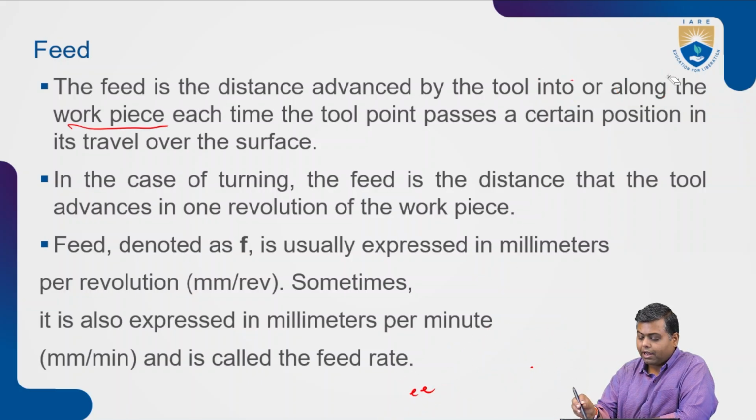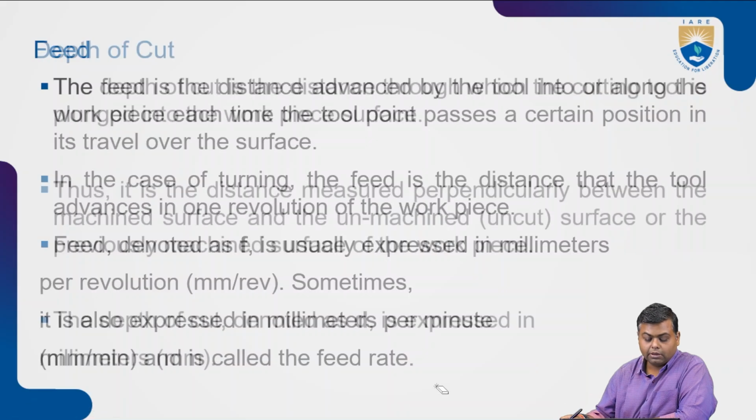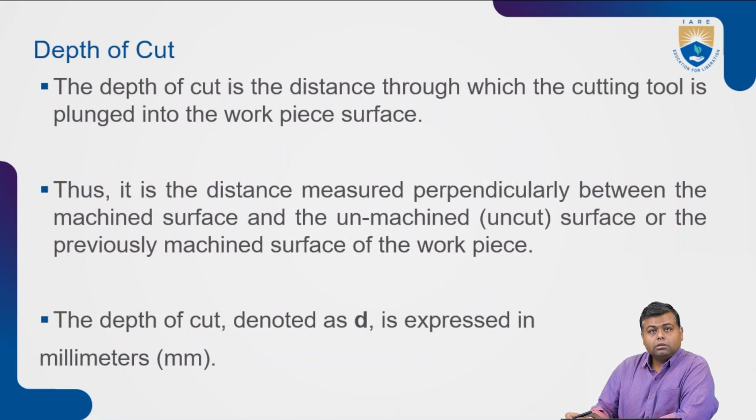Next, the third parameter we want to discuss is depth of cut. So depth of cut: generally when we need to remove material, the tool should plunge inside the workpiece. That plunging inside the workpiece is termed as depth of cut. So I can say in other words, the distance through which the cutting tool is plunged into the work surface.